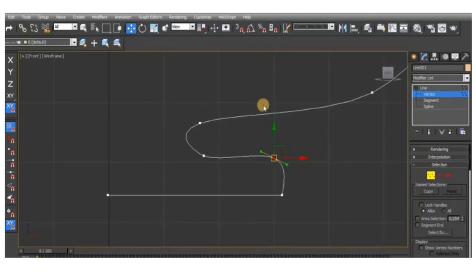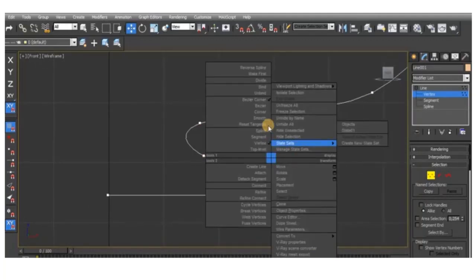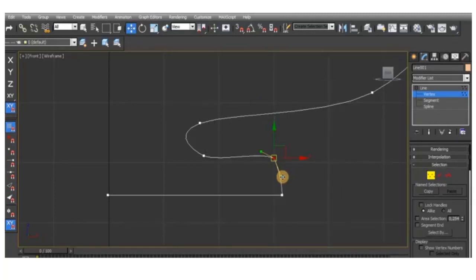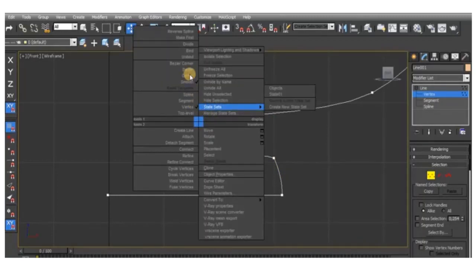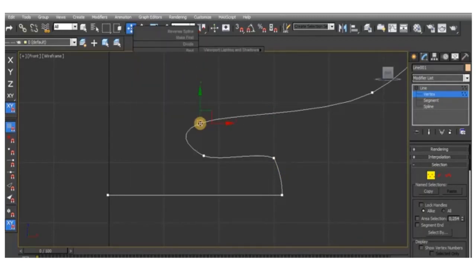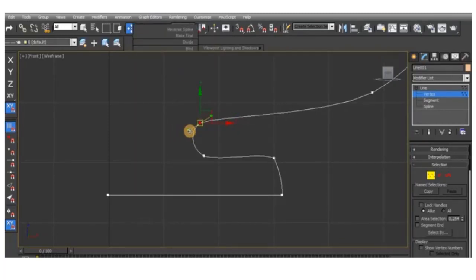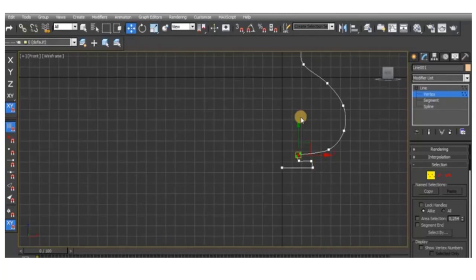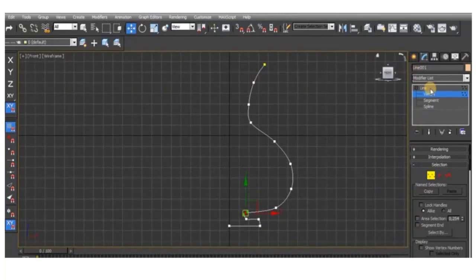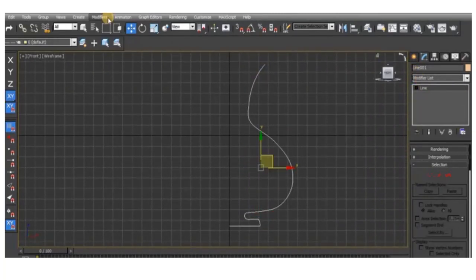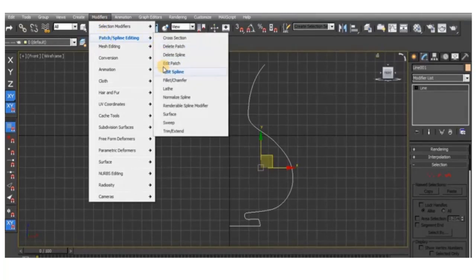You can use the lathe modifier to rotate a spline shape or NURBS curve about a specified axis. The lathe modifier is a shape modifier and is used to create 3D objects by rotating shapes about their axis. The direction of the axis of revolution depends on the pivot point of the shape.